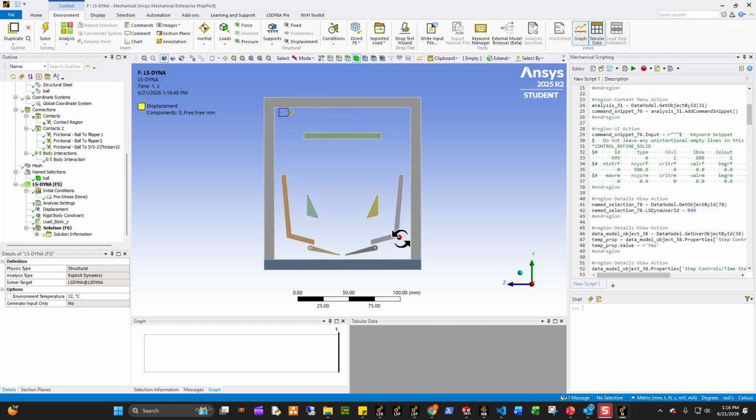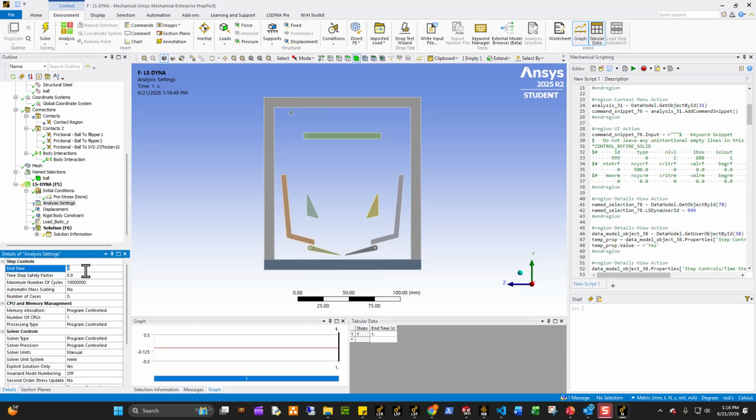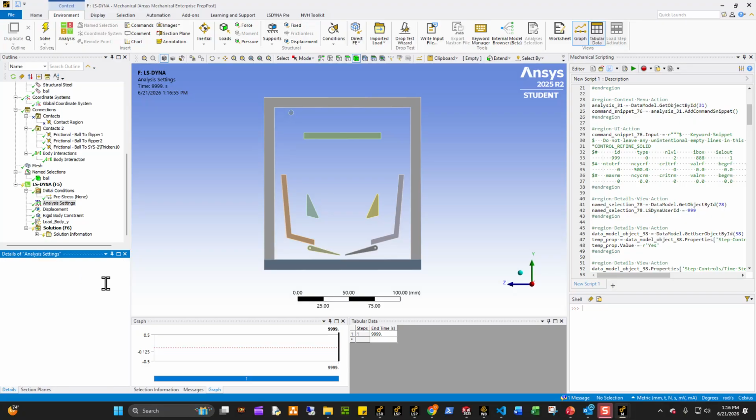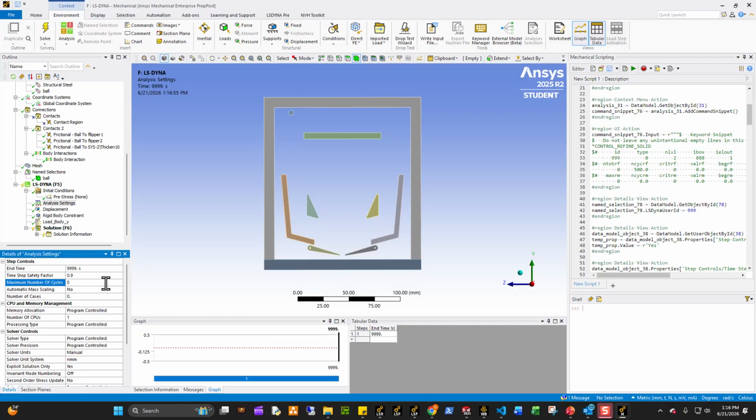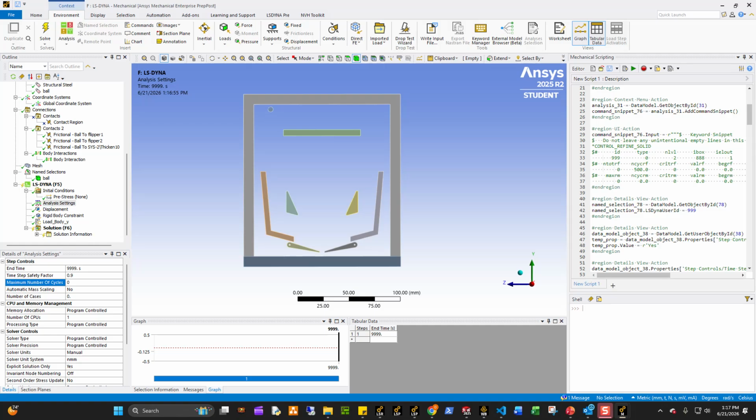Basically, what happens here is that as the model starts, it's going to drop down, it's going to start hitting everywhere, and then you will have no termination unless you reach the termination time. For me, the termination time in this case, I'm going to set to something super long because I'm going to terminate it with a sensor, right? So I don't want to terminate prematurely. And then I'm going to basically allow the model to just run essentially forever. Okay.